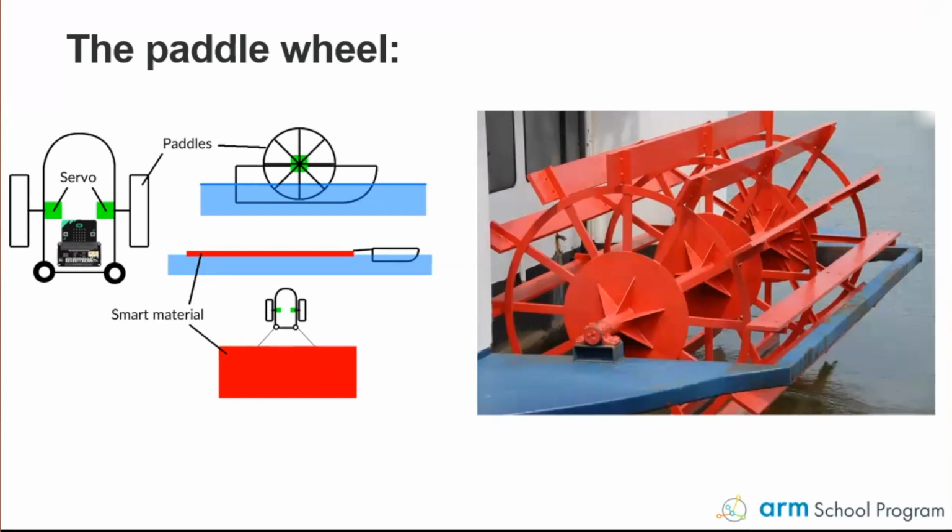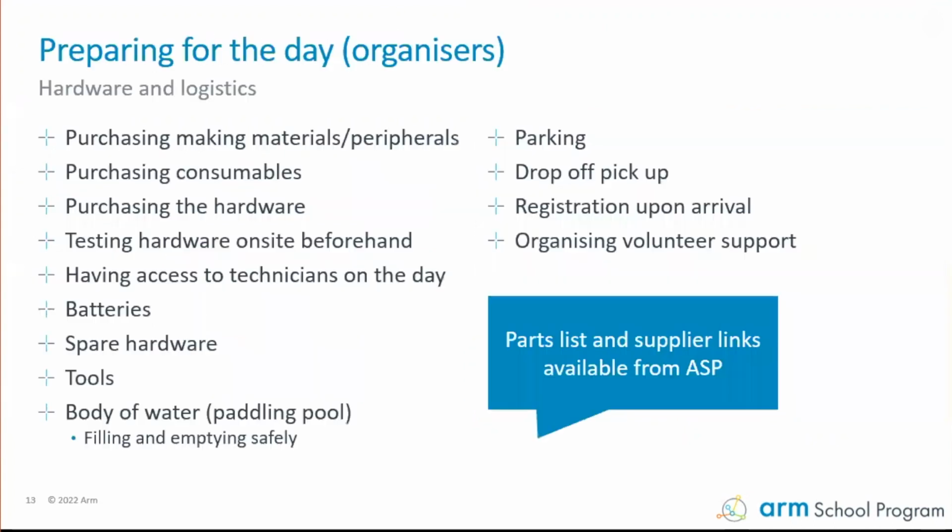But yeah, that typically is the bit that comes unstuck with students, because it's more of an engineering challenge than it is anything else. You can get packs from various suppliers which have the motor and then a sort of Lego clip that goes over the top, and you can screw that to a bit of wood or a bit of cardboard or whatever. And then the servos tend to have a flat section on a round spindle, and then you can stick the wood or the cardboard or whatever to that. So there's various ways of making this work, but something to consider.